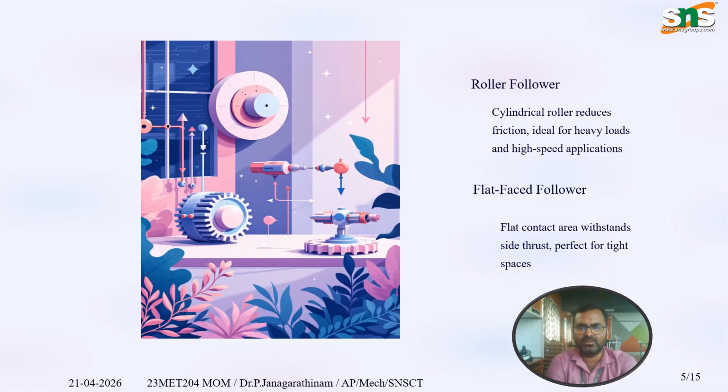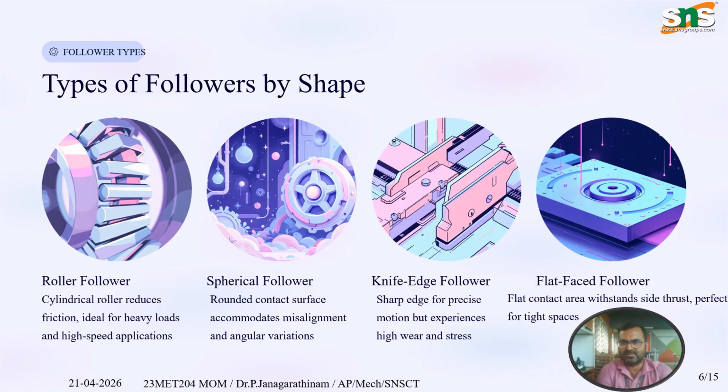Roller follower: the cylindrical roller reduces friction, ideal for heavy loads and high speed applications. Then the flat faced follower. These are the different types of followers. Flat faced followers have flat contact areas that withstand side thrust, perfect for tight spaces. So types of followers by shape are classified into the roller follower, spherical follower, knife edge follower and flat faced follower.